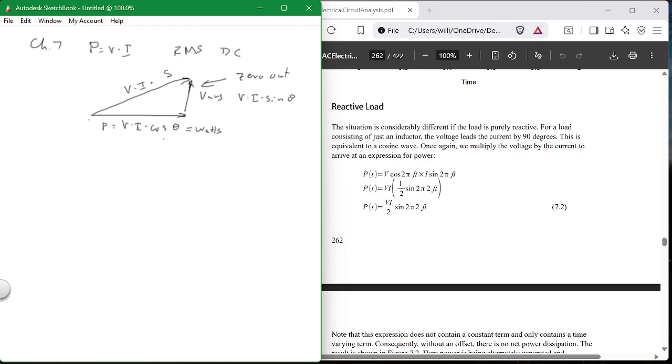Now you say, but motors are not 100% efficient. No, they're not. So then you devalue this to get what it actually turns to turn the shaft in the conveyor, because you might have a reducing gear, you might have other gears, you might have other things, and each one of those takes some power away from this. This is the starting point for what you get out. Everybody understand that? There is an inefficiency. To get a shaft turning on a conveyor, you have to do this times 0.8 or 0.7 or 0.9 or whatever. You don't get 100% of that out.